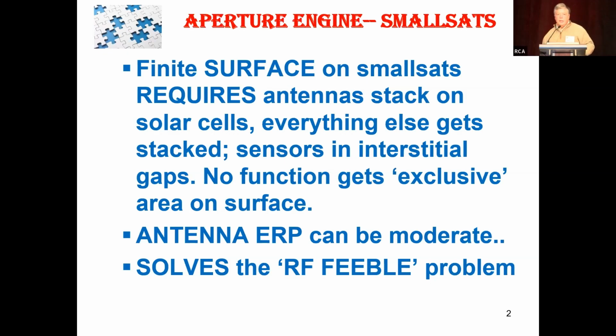It's going to have transmission line effect. I said, yeah, I know what it should do, but I'm going to do it anyway because I'm not being funded by a grant and I want to see what happens. So I did the layering, and it so happens that at S-band, at about a third of an inch, quarter of an inch, very, very close spacing from the solar cells acted like a very good back ground plane. I didn't have a lot of transmission line effect, and the antennas worked pretty well.